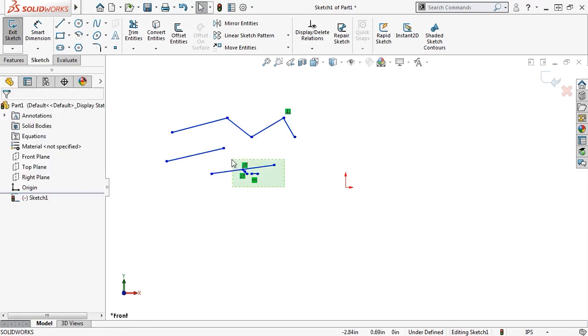Dragging from the right to left will select any elements inside of the box or crossing the box boundaries. This time, notice the box selection appears with a dashed line. When I press delete, they all go away.